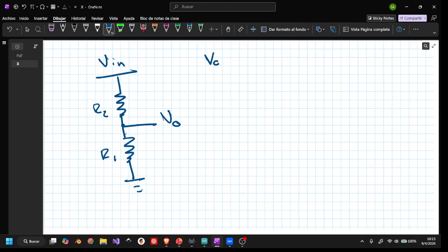Almost the other way, yes. The output voltage is the input voltage times the resistor that is connected to the lower voltage. In this case, it's called R1. Maybe your formula is okay if I name the resistors the other way, right? Over R1 plus R2, the sum of both. The numerator should always be smaller than the denominator. That's always true because the denominator is the numerator plus something else, okay?